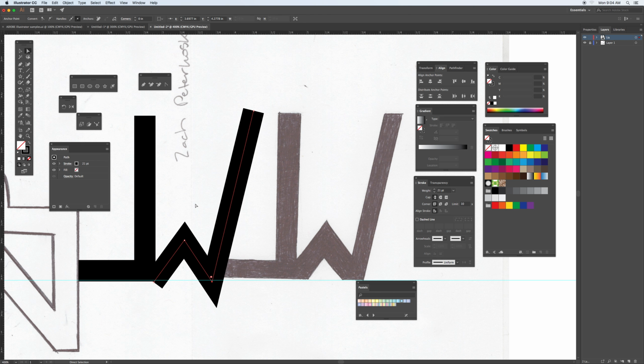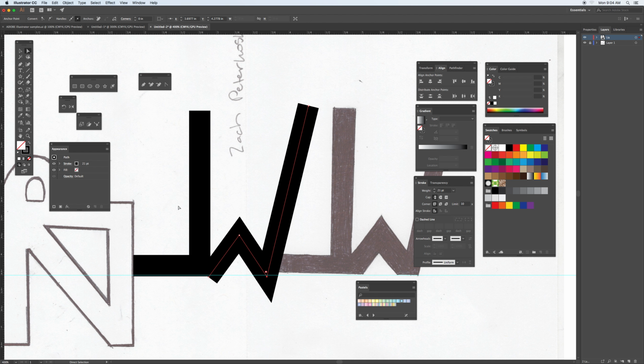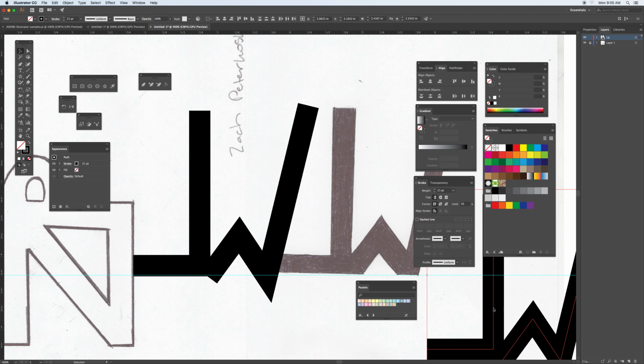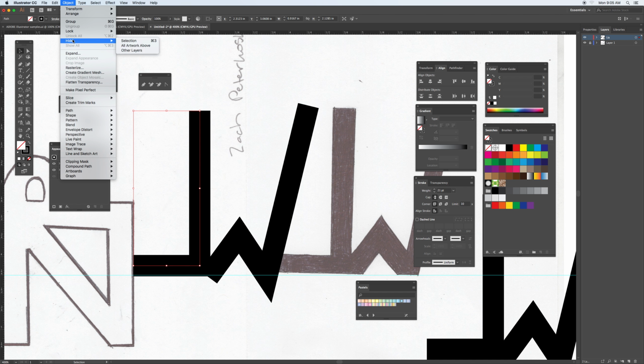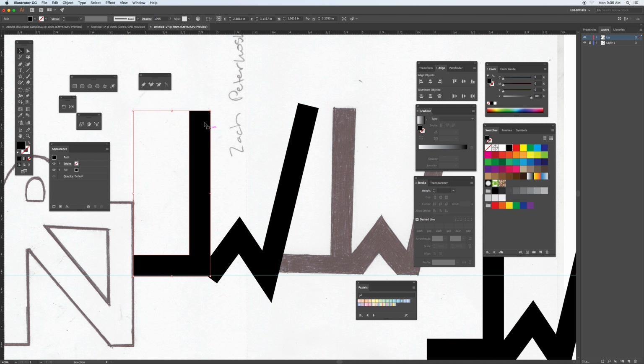Knowing that we've just dealt with geometric shapes, I could change all of this into a shape. We did it a couple of times, but let me just show you. Here's the initial part, and sometimes with Illustrator you may want to copy the items as you go and set them off to the side, in case you go a little too far and can't go back to that stage. Here's the stroke. I'm going to go to Object, Path, Outline Stroke. Now this becomes a shape.